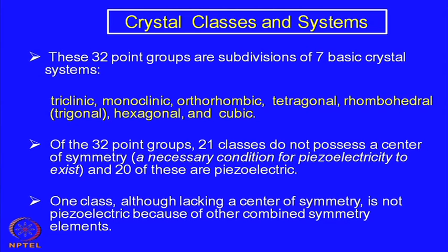Their symmetries are different, as you may imagine that cubic is the most symmetric, okay, whereas triclinic is the most non-symmetric. So, this is how the order changes. We have seen, particularly in the case of barium titanate, that there are 4 different polymorphs: cubic, tetragonal, orthorhombic and rhombohedral.